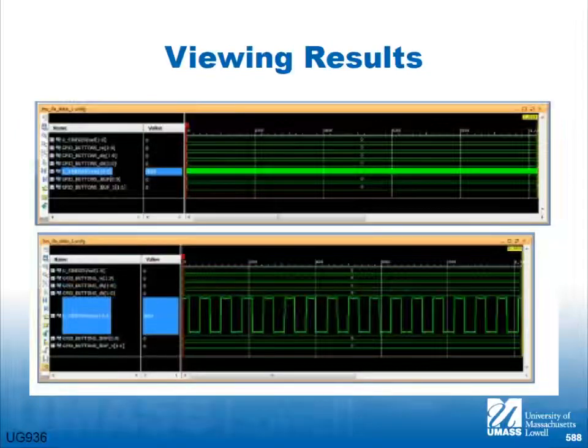So if you're trying to simulate a very specific part of your ASIC, you can load it into an FPGA, just compile it into an FPGA, use this tool to give you observability of the part, and you can do your simulations effectively in real time, as opposed to waiting for a long sequence of events to happen in simulation.